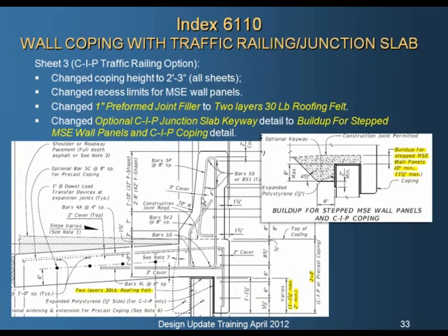Same changes have essentially been made for the cast-in-place traffic railing version, and we've also updated the bond breaker material between the top of the wall and the underside of the slab, and tweaked some of the details for the cast-in-place keyway on the cast-in-place coping to accommodate the stepping of the panels.